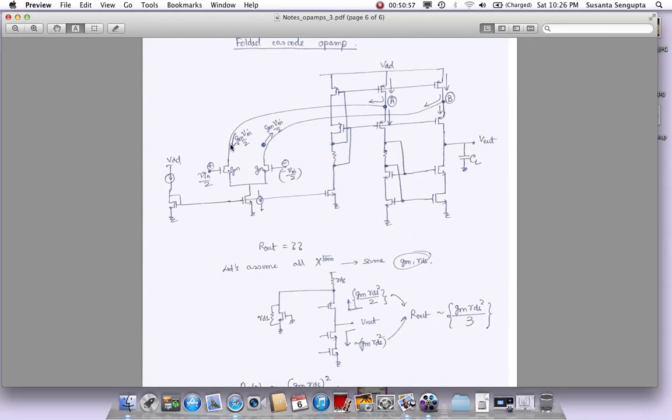And what is happening is we are taking this current and then we fold it down the stages. I'll explain the stages more. Since we take this current and we fold it down and eventually create a voltage, these are called folded cascode. The outputs are cascoded. The input currents are folded, and that sort of gives us the name folded cascode op-amps.